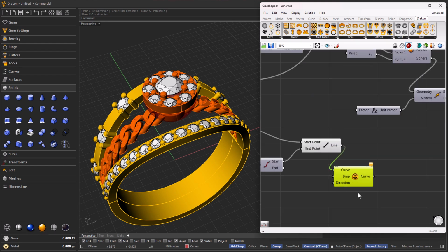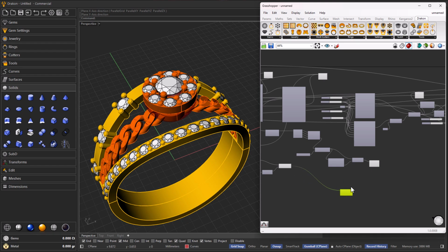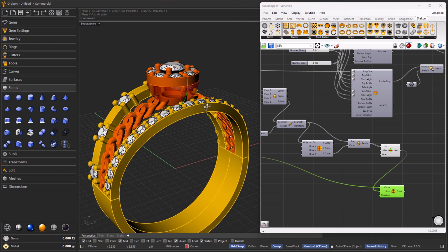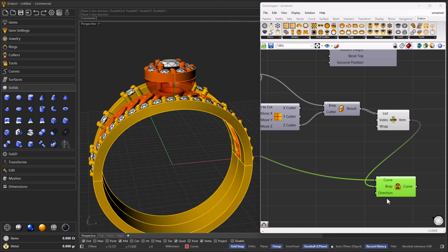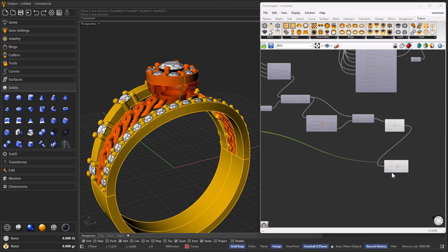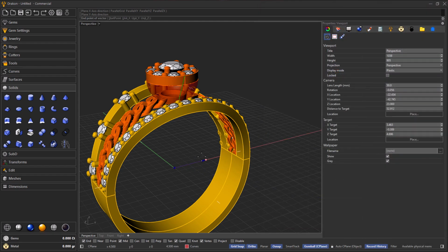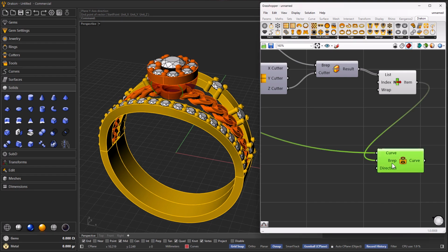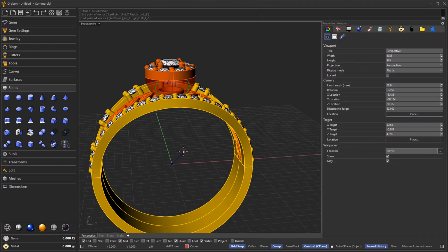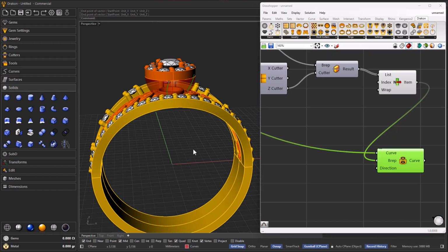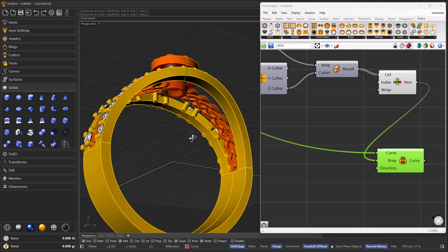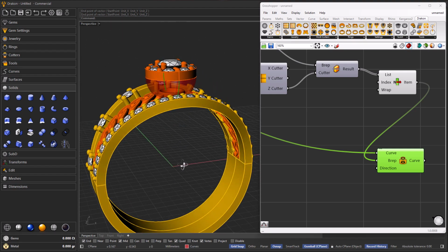Okay, so for project, the item is the curve, and the brep is the sphere that we want to project onto. Let me set the direction of the projection, so I'm creating the curves. Let me check other directions to see the results. If you tap set on vector in Rhino, you set the direction of the axis.